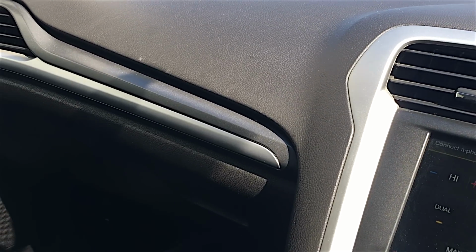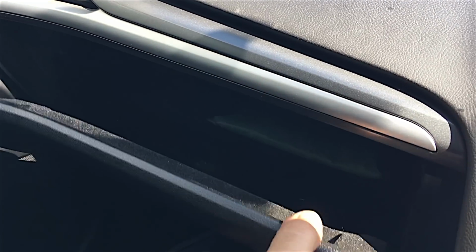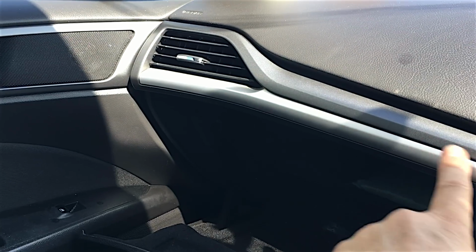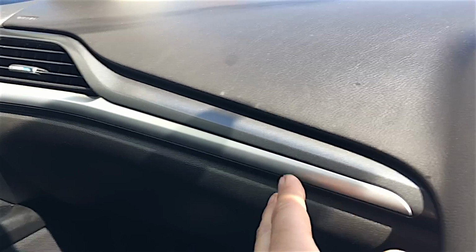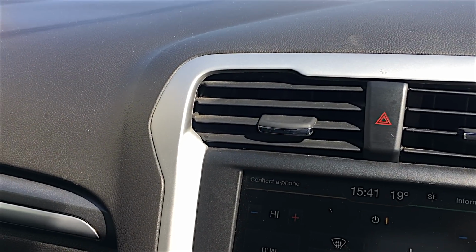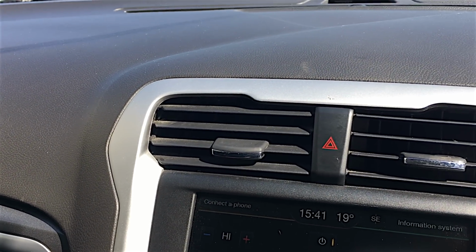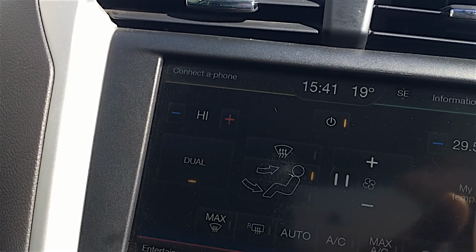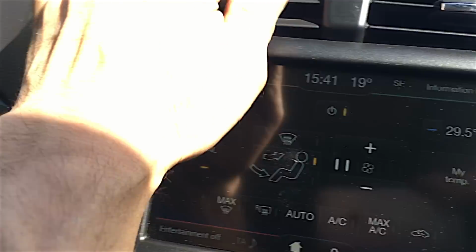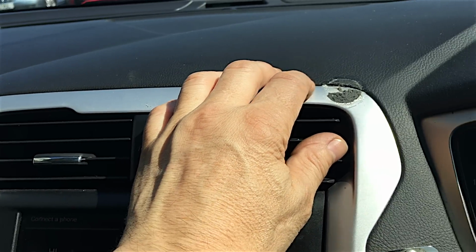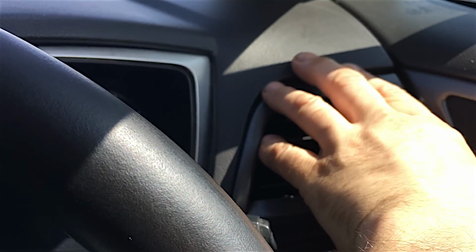Okay then, we're all back together. I have just fitted a pollen filter, which involves removing the glove box and this passenger side vent, as there wasn't much air coming out of these vents, and I took the pollen filter out and it is flipping well blocked. I'll show you it in a minute. Anyway, I've got the heater set to high, so I've got nice warm air coming out the passenger vent and out of the driver's side vent and the end vent, so that's good. That's all nice and hot.